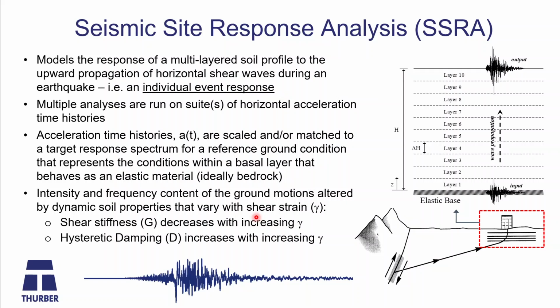So what is seismic site response analysis for anyone that's not familiar? This is basically analysis that models the response of a multi-layered soil profile to upward propagation of horizontal shear waves during an earthquake, okay? So it's the response to an individual event. It's important. I want everyone to realize that's what the analysis is. We're saying, how will the ground respond to an earthquake?